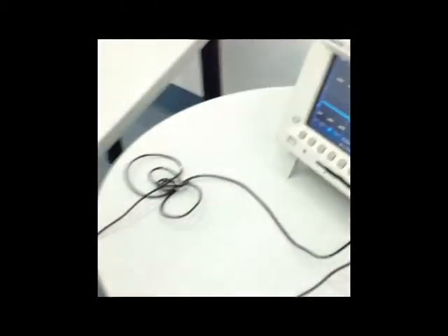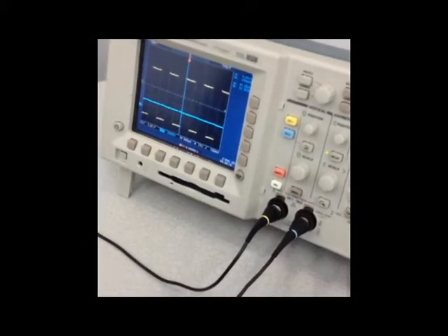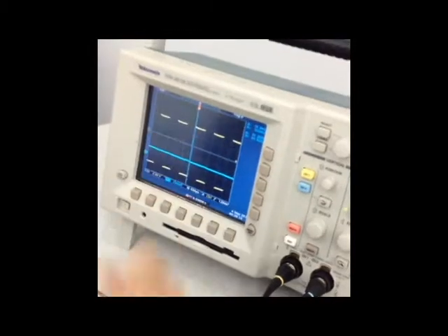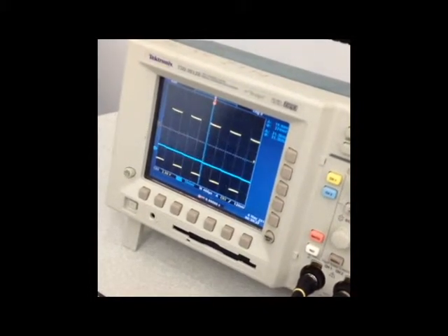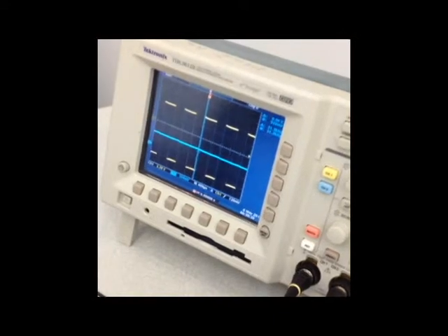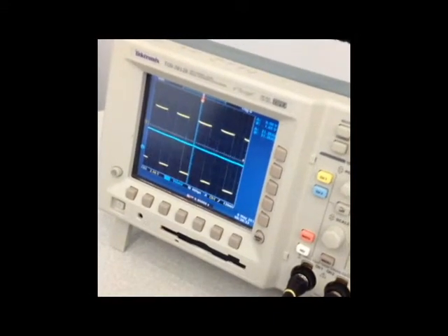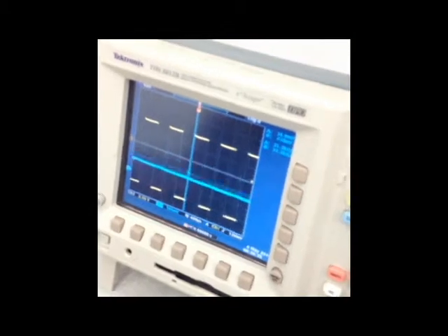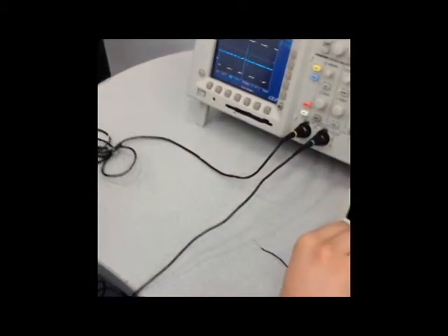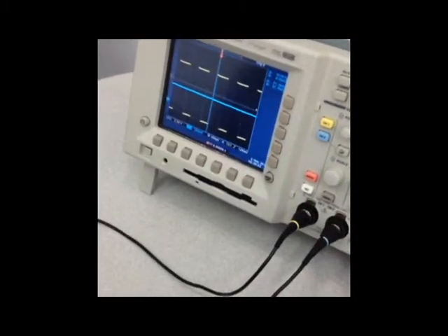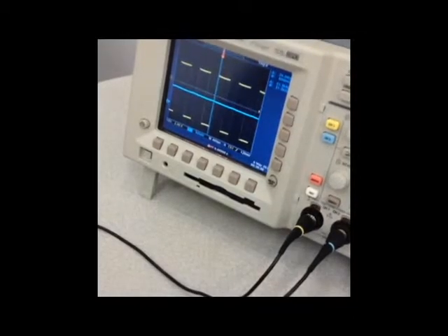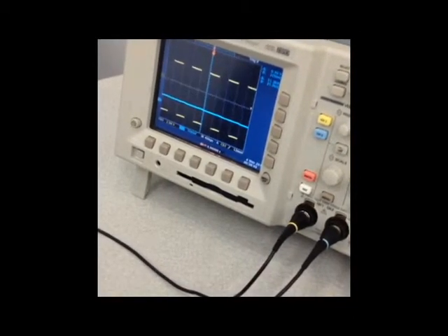Okay, so we have here a demonstration of the voltage controlled oscillator. As the output of the loop filter, which is the blue line, changes, the VCO's output changes as well. I'm controlling the loop filter right now by changing the input frequency to the entire system, and you'll notice that as I go to a lower frequency on the function generator, the frequency of the 555 also decreases. So that is correct behavior.